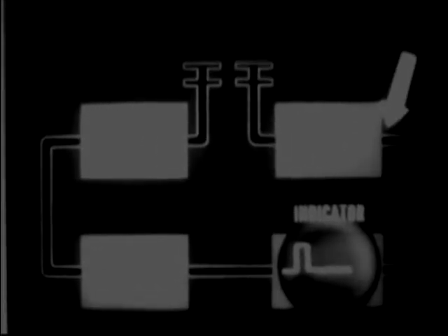The sweep of the baseline is synchronized with the outgoing pulse, so it can measure the time it takes a pulse to leave the transmitter, reach a target, and its echo return. When the outgoing pulse strikes a target and part of the energy is reflected back to the radar set as an echo, the receiving antenna's job is to pick up the returning echo and shoot it along to the sensitive receiver. Here, the weak echo is amplified and sent as a voltage pulse to the indicator, so it can appear as a target pip. Basically, that's how all radars work.